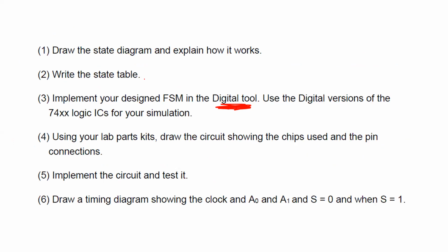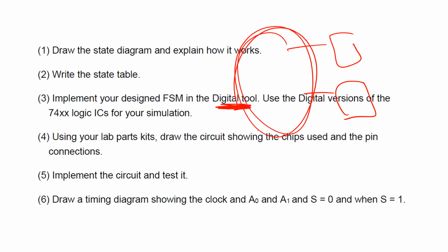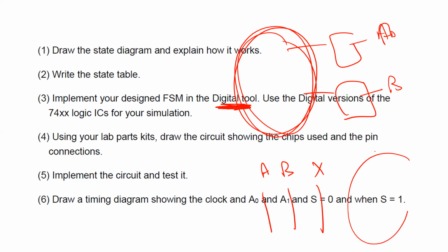So here, once you have the circuit, you should have two flip-flops, and then here a combinational circuit. This combinational circuit should function as a relation between A and B, and you have X as well. So you have to put all possible cases, and then you need to see what the next state is, as I said in the lecture, and then see what you should put at the input here.